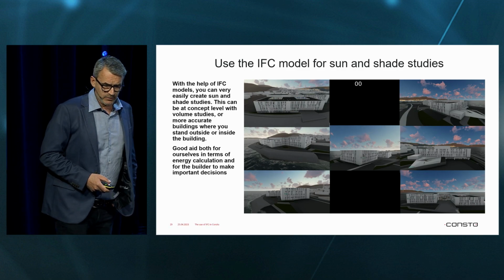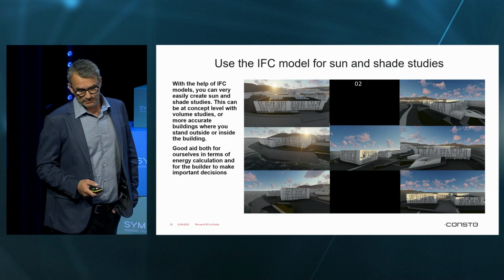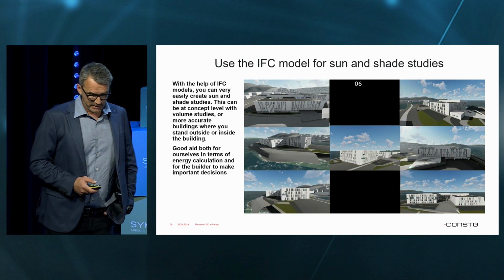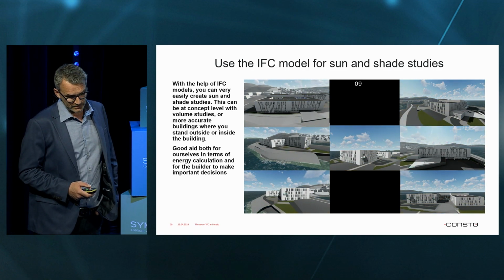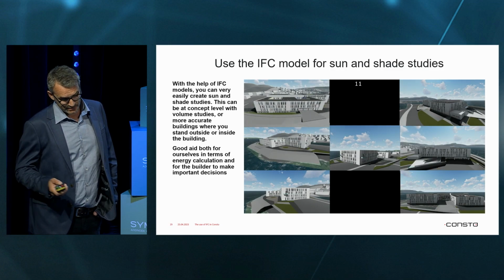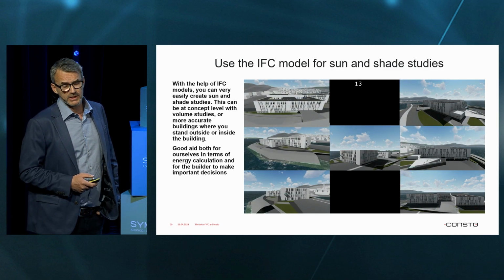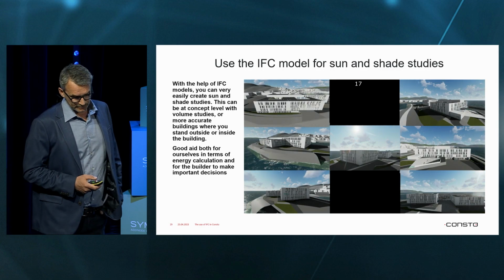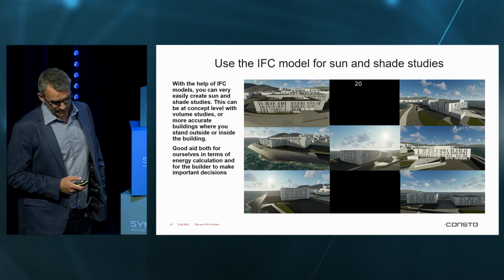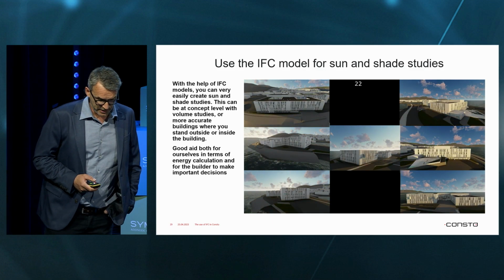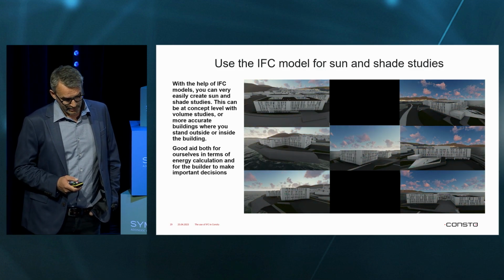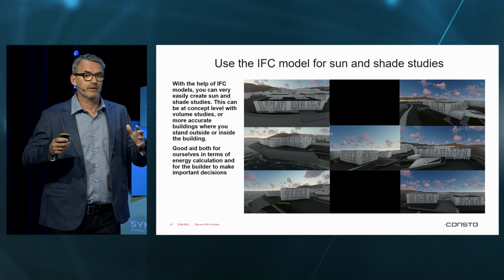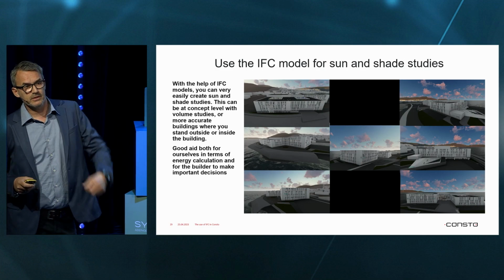Yes. And we use the IFC model for sun and shade studies. With the help of IFC models, you can very easily create sun and shade studies. This can be at concept level with volume studies, or a more accurate building, where you stand outside and inside the building. Yes, a good aid both for ourselves in terms of energy calculation and for the builder to make important decisions. And here we take the model, put it in the direct, correct location in the world, and run the sun study.